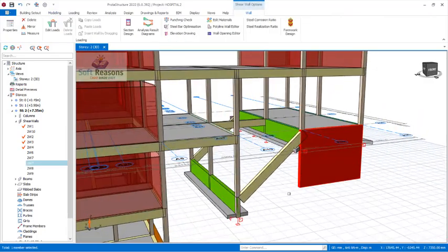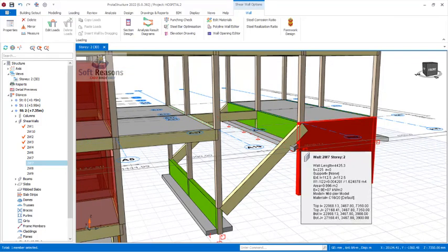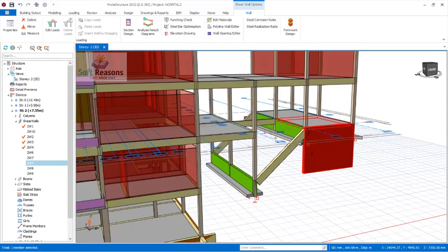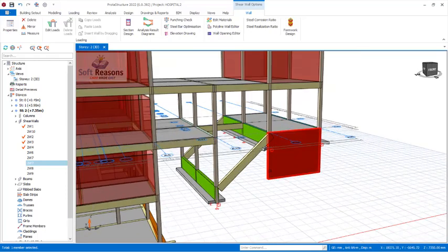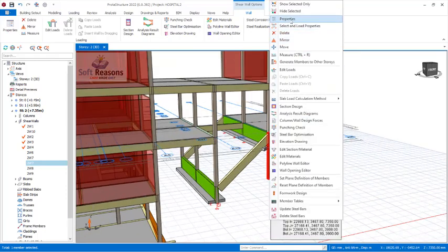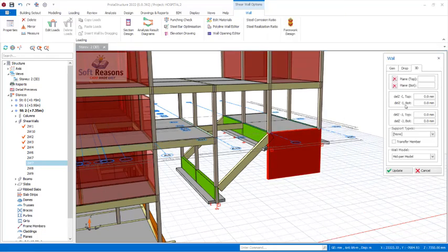You have to select this shear wall, since you know the foundation depth to be anchored at this point. So you have to subtract the whole of this story height off from this shear wall height to get your foundation successfully. So you have to select the shear wall, right click and then select property. In the property dialog, navigate to the 3D and then you can see the height bottom directions. You can now key in 3450 right there. Okay, just like this, this is 3450.